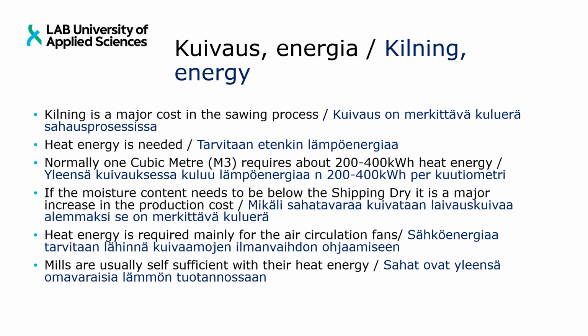So therefore, if the moisture content needs to be taken below the shipping dry, there is definitely an increase in the production cost. And also we have to remember that if we take the moisture below the normal shipping dry, then the shake, twist, and cupping come more into the picture. So when costing especially kiln dried goods, one has to take into account both the actual cost of drying and also the increase in the defects which you need to downgrade.